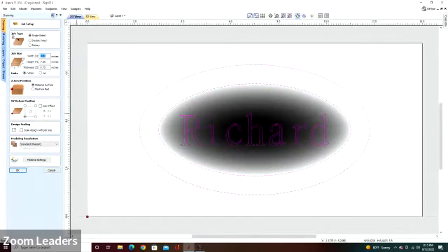And you can say, okay, we've got the X and the Y defined, but we also want to know whether we're going to reference the top of the workpiece or the bottom of the workpiece. And that's done here, Z0 position, material surface, or machine bed. Okay, question, since that board could be anywhere on your spoil board, how do you tell it where that corner is? We'll do that in a minute. So right now we're doing the design work. And if I tell it wrong over there, all kinds of funny things happen. We make plenty of sawdust.